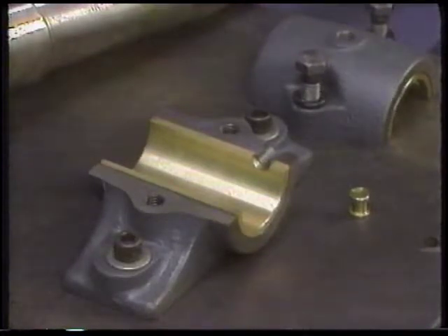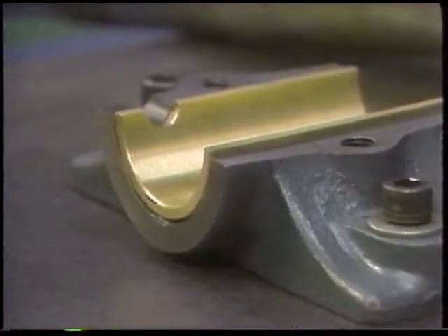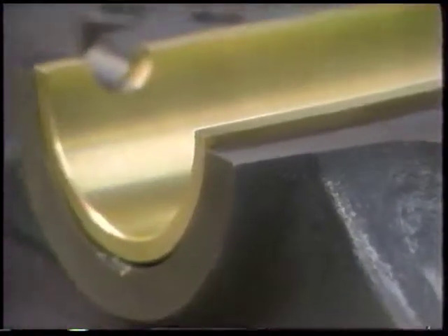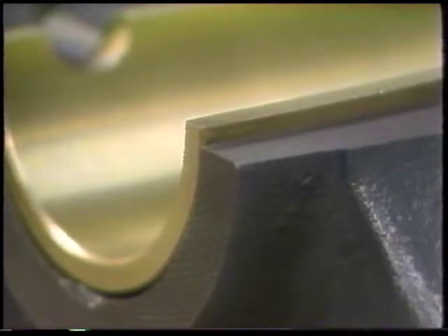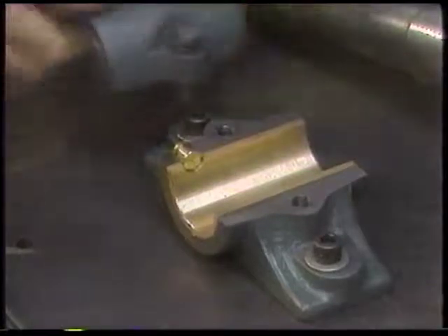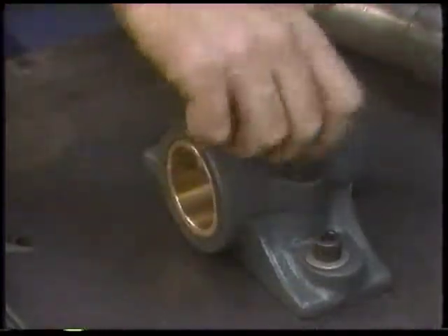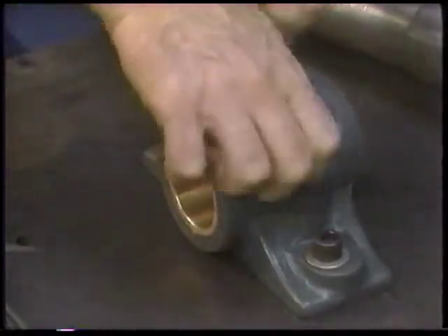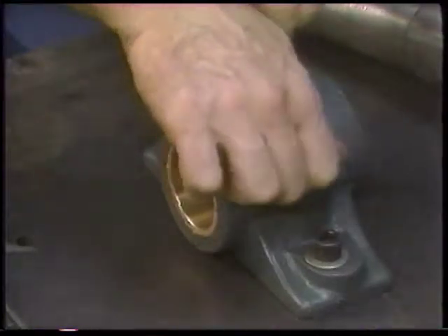Usually, a dowel, screw, spool, or lug is used to keep the bearing in place and prevent rotation. If the edges of the bearing shell project slightly above the split housing surface, do not file them flush or try to shim the housing. The edges help secure the bearing in place when the housing is reassembled. Finally, always tighten the housing bolts to the correct torque.